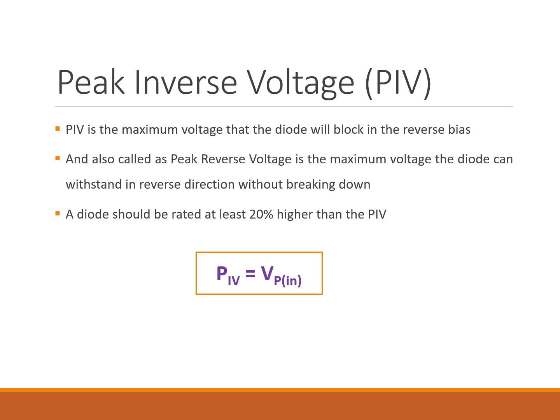If you've got a diode or a component that can't handle that voltage and your reverse bias voltage is much higher, you're going to physically deteriorate, burn the component. So there's a safety rule that engineers use. We don't normally ever make it that close. We use a safety margin.